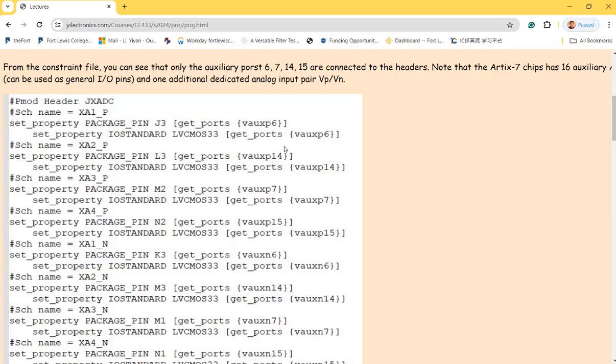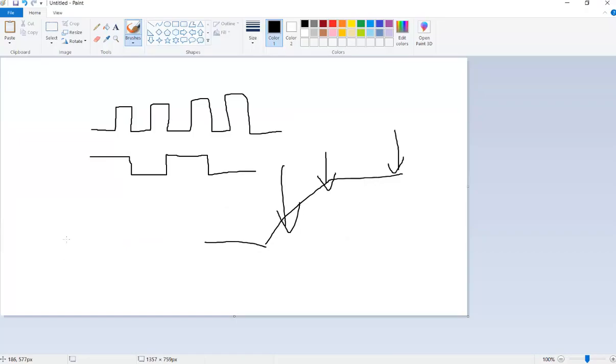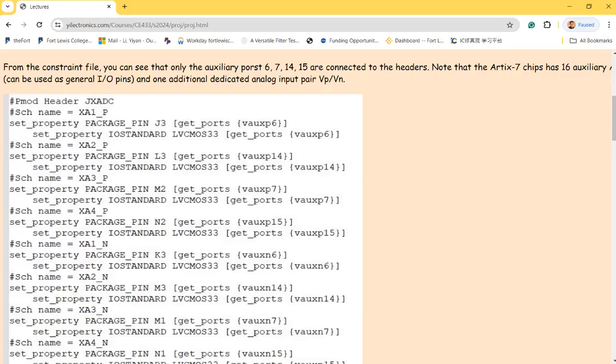I don't know if you guys have already taken this. It could be in circuit 1 or in analog. It covers the amplifier configuration called a difference amplifier. It's taking a differential input. So you got an op-amp, right? You got 2 inputs. You could have 2 signal lines, or if you ground one of them and give a signal input to the other one, it's actually taking the difference of the 2 inputs. So you use this one minus this one as a voltage input. It doesn't matter. Let's just ground one of them.